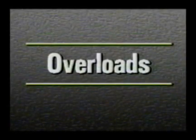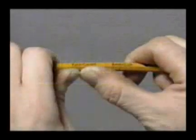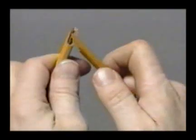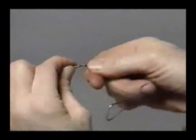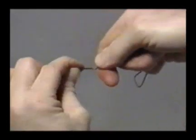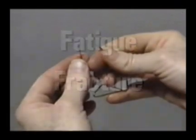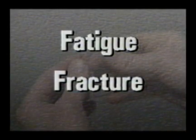Parts often fracture because applied loads are greater than the part can carry. With severe overloads or shock loads, fracture sometimes occurs during a single load application. These fractures are referred to as ductile or brittle fractures. Other times, the overload is cyclic, and fracture occurs after many repeated load applications, as is the case with this paperclip. These types of fractures are referred to as fatigue fractures, since the metal appears to tire after many load cycles.